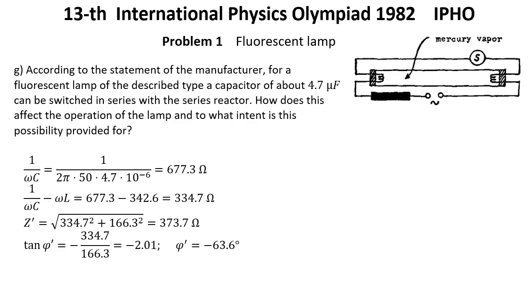That is, a high portion of reactive current is unwelcome, because the power generators have to be laid out much bigger than would be really necessary, and the transport losses also have to be added, which are not paid for by the customer if pure active current meters are used. So that was solution for question G.